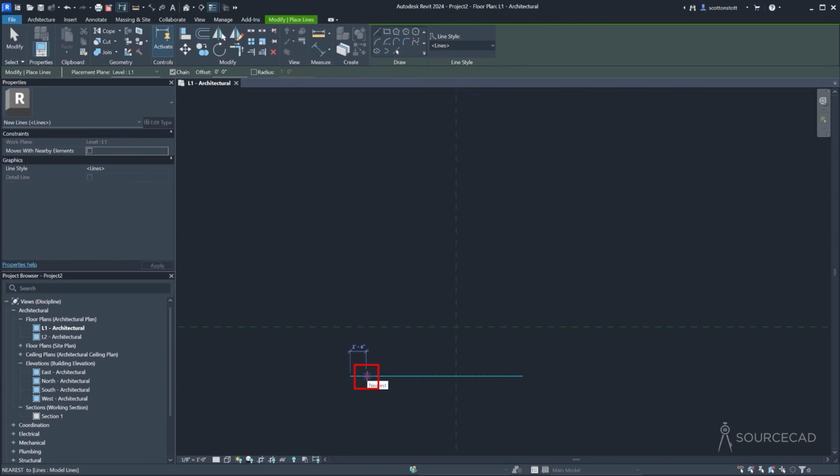It's a magenta X. And this represents the nearest snap. Nearest means it's somewhere along this edge. It's on the edge, but it could be anywhere really. And if I move the cursor over more, at some point, we're going to see the midpoint symbol, which is an equilateral triangle. And so each object snap has a different symbol that you'll become familiar with in time.